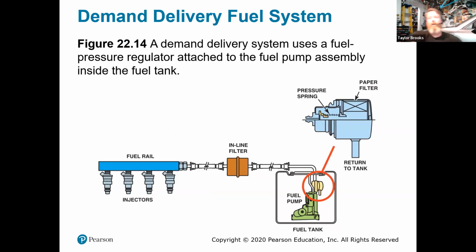When it is on the fuel pump, typically we're going to have it dampen the fuel pulses into what's known as a surge tank. This is a good idea to have on any fuel system, where you're feeding from a larger tank into a smaller tank, and the goal is for that smaller tank to always be full. So anytime you have a surge in power, you have proper fuel supply.